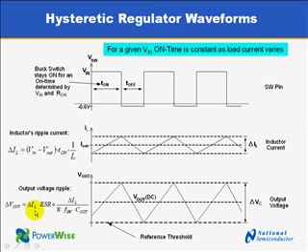So by choosing this value, you can mainly influence the ripple of the output. The second factor is the inductor current. The inductor current ripple is determined by this formula. It's dependent on the difference of the input voltage and output voltage. This term is fixed, and there are two other factors. One is the on time. The on time can be chosen by selecting the right on resistor. And there's another factor contributing: the inductor, which the designer can also choose. So these two, the T on and the L, give you the value of the inductor ripple.